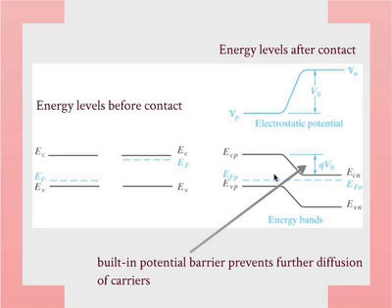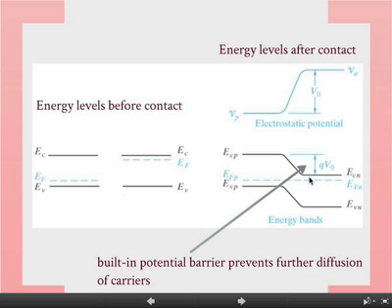But you cannot have current in equilibrium, which means that something must prevent it from moving from left to right. Otherwise you will have current. And that something is the field. Okay, and which way is the field pointing? Which way would the holes flow if there was no field? I just said that. From p-type to n-type, right? From left to right. So the field has to prevent it, needs to point from right to left. Remember, holes always move in the direction of the field. So the built-in field is pointing from right to left in this case.